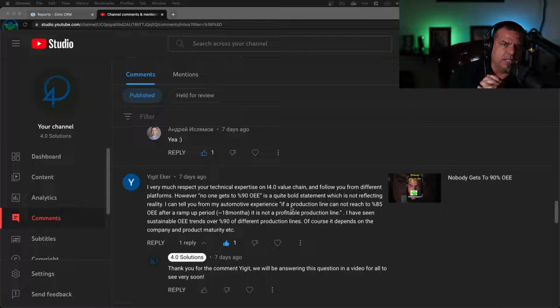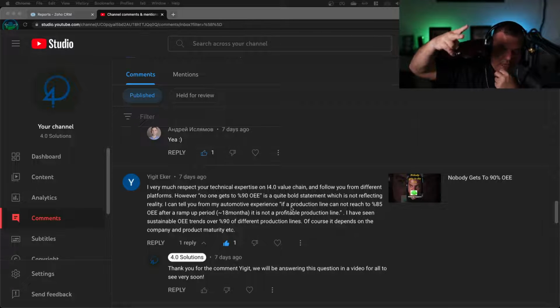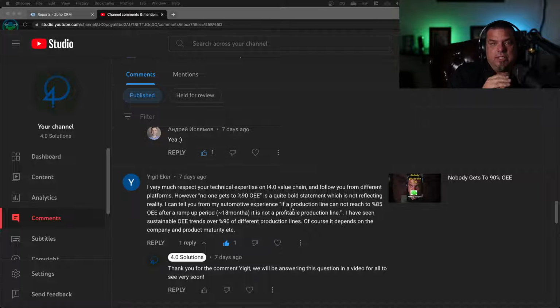They were calculating their OEE around 82, 83% religiously over the previous 5 years. We built a digital manufacturing execution system that accounts for rework, that accounts for the downtime, which they weren't calculating. And we use the standard OEE calculation. And their worst performing line had 26% OEE. Their best performing line had 42%. They were calculating it at 82.